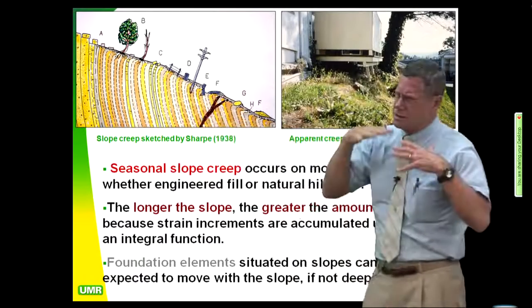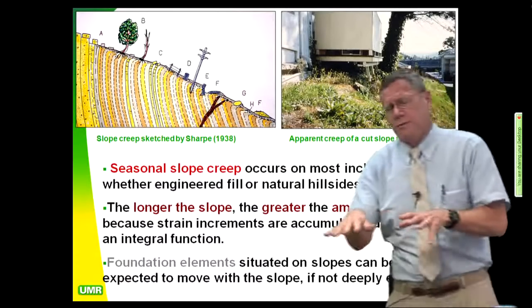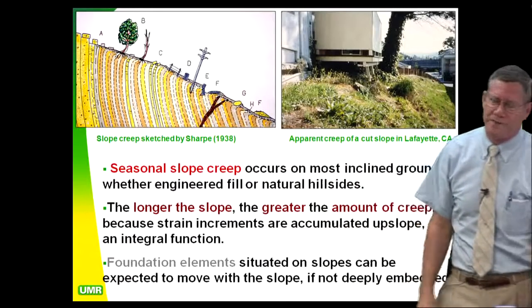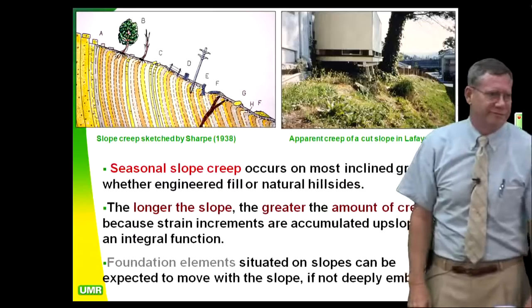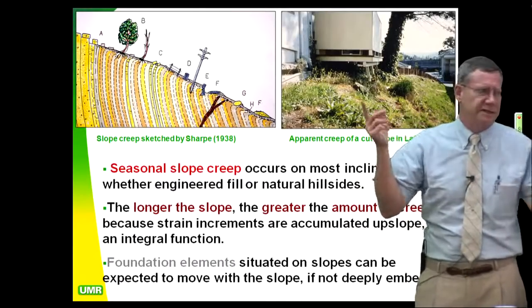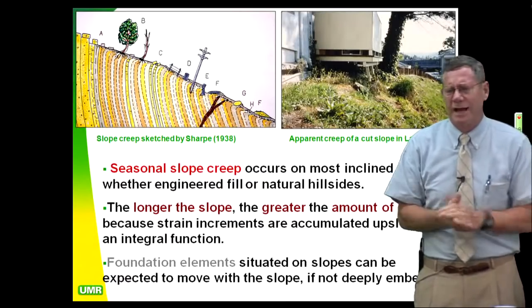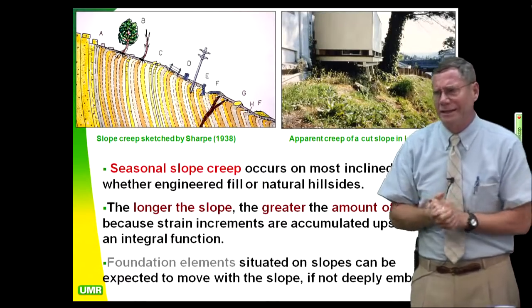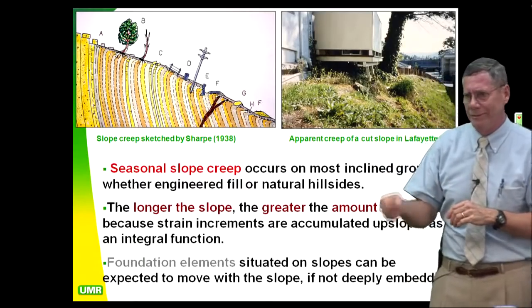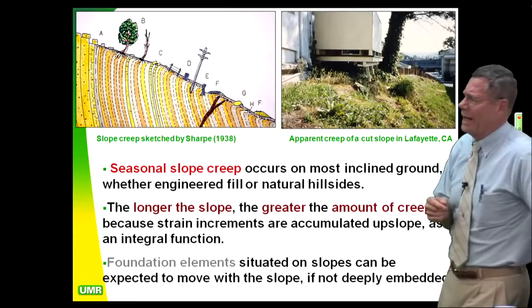They got lots of things creeping down the slopes. When I found the hot zones that were really creeping a lot, they were always broken pipes, corroded pipes, and they were just weeping. They didn't have the sonic velocity testing. They didn't hear anything. Well, you don't have to hear anything to get a million gallons a year at one spot. That's just a little drip, drip, drip, drip. That's 1 million gallons a year. You can do the math on it yourself and figure it out.